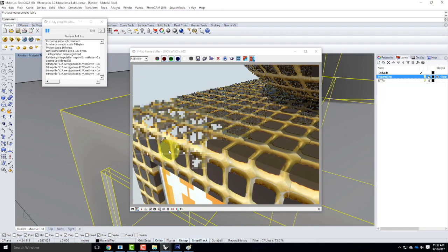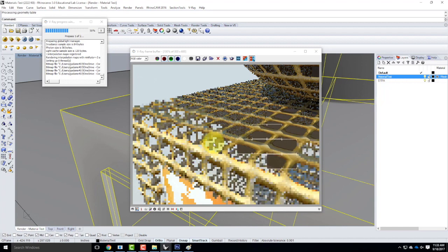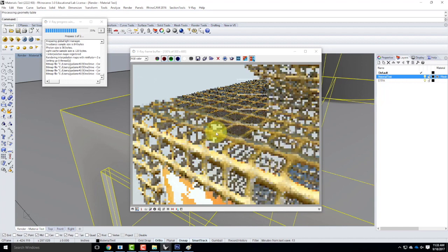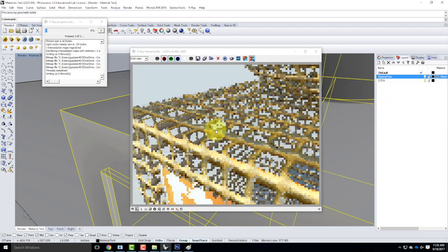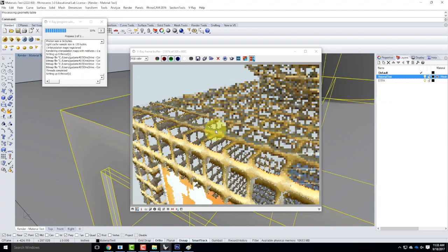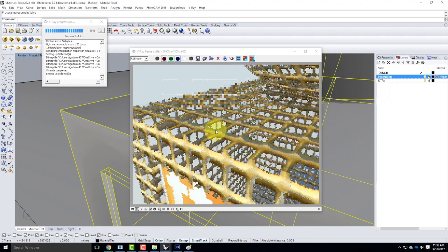it's going to take significantly longer because it has to calculate the light passing through the mesh in multiple layers. But you can already see that it's transparent. So it's through these objects that I create these materials. Now obviously there's other parts to the material. In this particular material, because it's kind of a yellow plastic, it has some reflection to it. So I need to adjust for that glossiness or that reflection. So depending on the material, you may have to do more. The cedar shingles probably don't have any gloss assigned to them, so that's not too big of a deal. So depending on what you're creating, if it's metal, it would have more gloss than if it didn't. So there's little bits that will have to be resolved as part of this process.